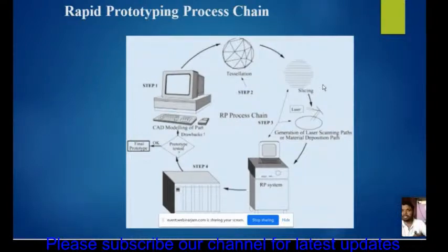While saving that in the SD card, the slicing software will change that into a G code, the machine language for functioning of the machine. The machine will read only the G code and M code, so it saves the sliced file in G code for starting it on the machine.